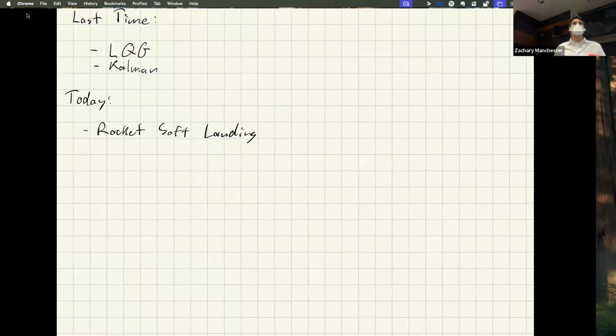Yeah, there were a bunch of things. In particular, Perseverance was the first to use TRN, the vision-based terrain relative navigation. That was the new thing. Prior to that, they didn't really do TRN, and the error ellipsoids on the landing were a lot bigger. I think that's the biggest one. Otherwise, they were very, very similar.